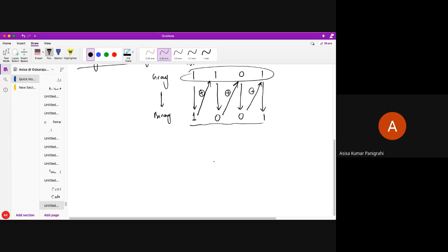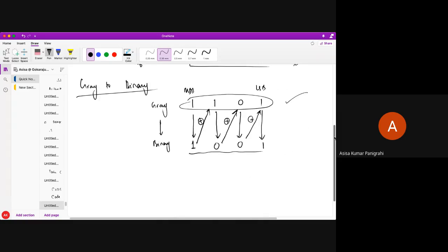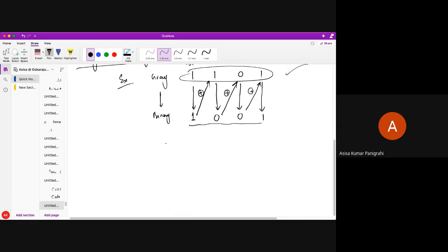So this is the actual thing. If a question comes, what you need to do is construct this block diagram and make a logic like this. Gray code to binary, take an example. This is the way we can make it, and you can simply draw the logic diagram. Very simple, students. You can take G3 here as input. G3 is equal to your B3. Am I correct? I am copying the MSB. For your binary, MSB is also the same as G3.